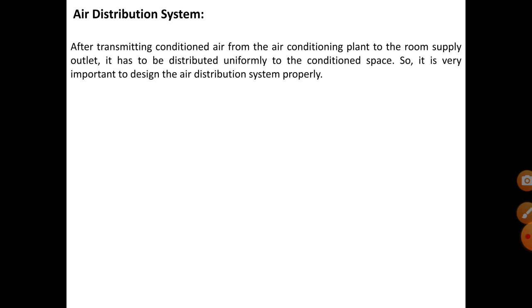Certain terms you can come across when you deal with air distribution are intake and outlet. These are simply openings, the openings provided for supplying the air or returning air that would be used as recirculated air. The different openings could be grills, registers, diffusers, etc. They are useful for distributing the air.